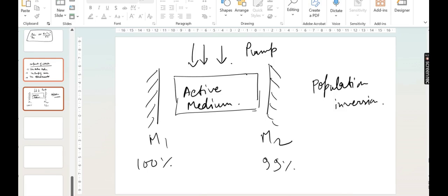In order to have optical amplification, the medium has to be kept in a state of population inversion. The pumping mechanism provides for obtaining a state of population inversion between a pair of energy levels of the atomic system, and when we have population inversion, the input light beam can get amplified by stimulated emission.